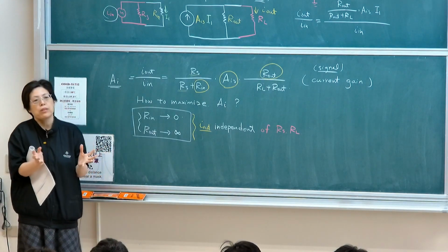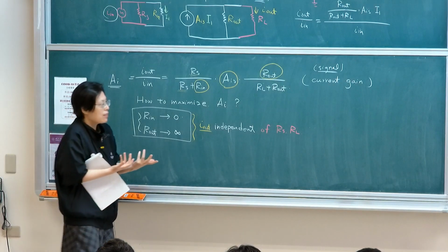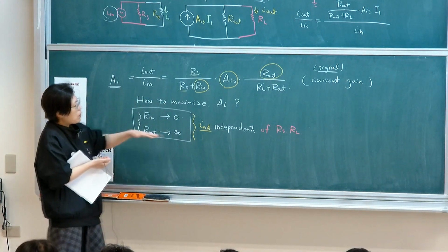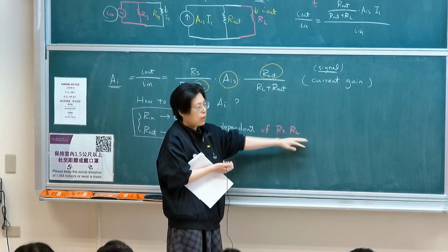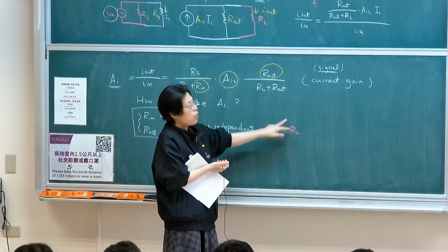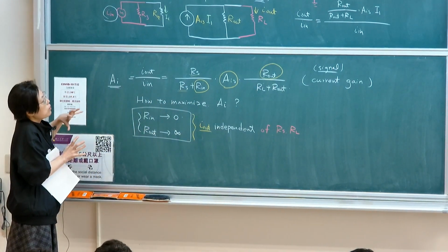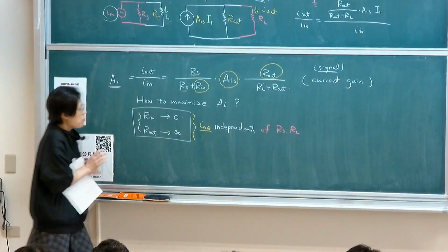It will always be 25 degrees inside. That's a robust design of insulation or whatever. This is the same thing. You want it to be independent of your source resistance and loading. We call this loading effect or source effect. You want to be independent of that. So that's why we want to have low input resistance. That is why we have the common base stage.